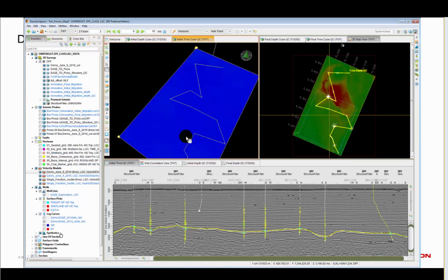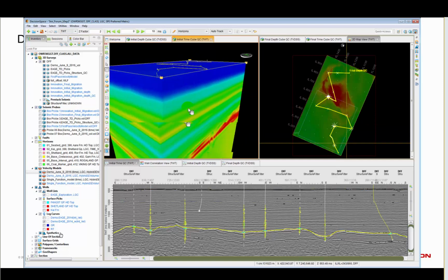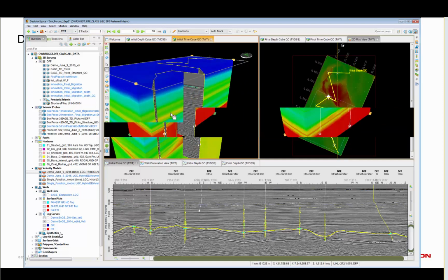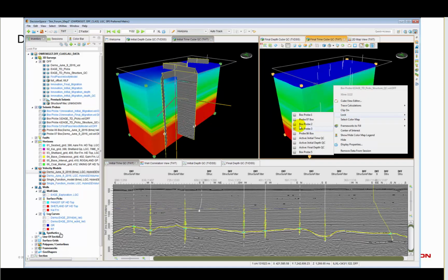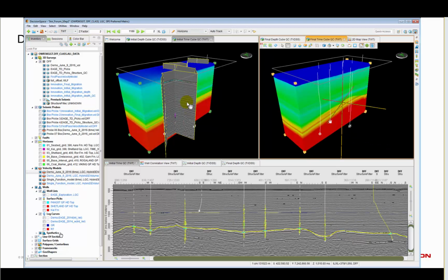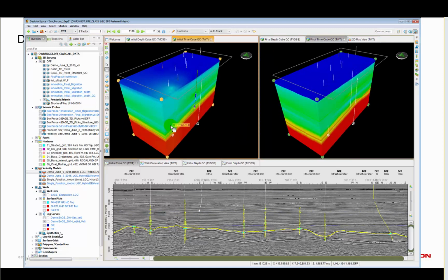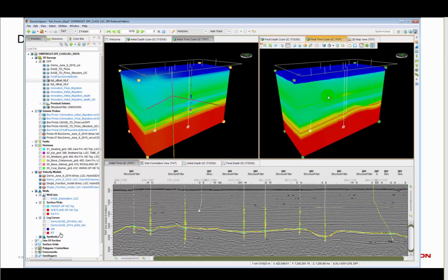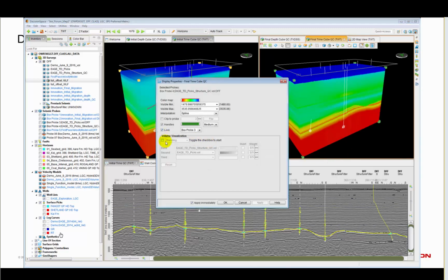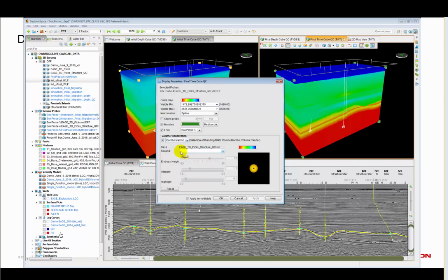And when that happens, it's loaded really just as a seismic volume. So you have all the power of seismic cube probe displays. So we can see now we are exactly inside the survey, and you get the power that comes with the seismic display. So you can lock the probes, you can lock the orientation. It's really good QCing two different velocity models together in this method. You can overlay them. And of course, you can use the power of the display properties for blending with the seismic if you want to in the dynamic world. You could also do combo mambos and volume rendering, RGB blending with the velocities now with this workflow.